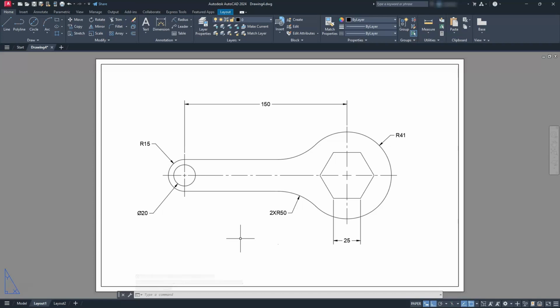So yes, short and sweet and easy and simple just to do your dimensions. Just remember that anytime you're dealing with paper space, you don't have to do a lot of stuff. It's really designed for this. So this is how most of your 3D software or parametric drafting software works. They work on the concept of using some kind of paper space or layout tabs with viewports and things of that nature, right? But there's absolutely nothing wrong in AutoCAD with doing it the other way.